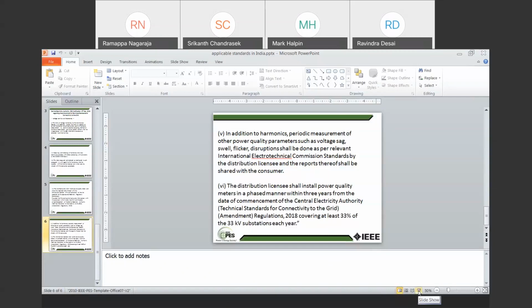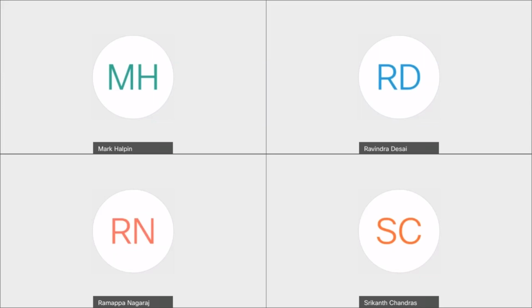Okay. The issue of CT and PT frequency response is a well-known problem. There is a general consensus that conventional CTs and PTs, meaning wire-wound CTs and PTs, have a reasonably accurate frequency response below, let's say, 1 or 2 kilohertz.